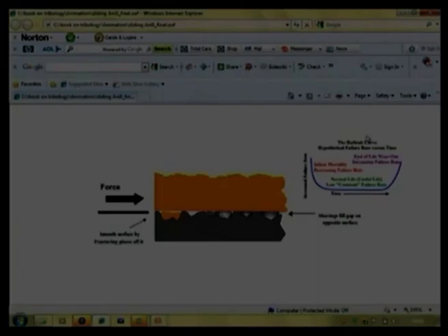That is why when we refer to this bathtub curve, we say there is a possibility of very high initial wear rate. It slowly comes down, reaches a steady state condition, and after a certain duration it increases. We say that this is infant mortality, that means in childhood the material is bound to wear out more. Then it will reach normal life, where it has to show its own function. When that functional life is over, the wear rate will increase. This is the end of component life.